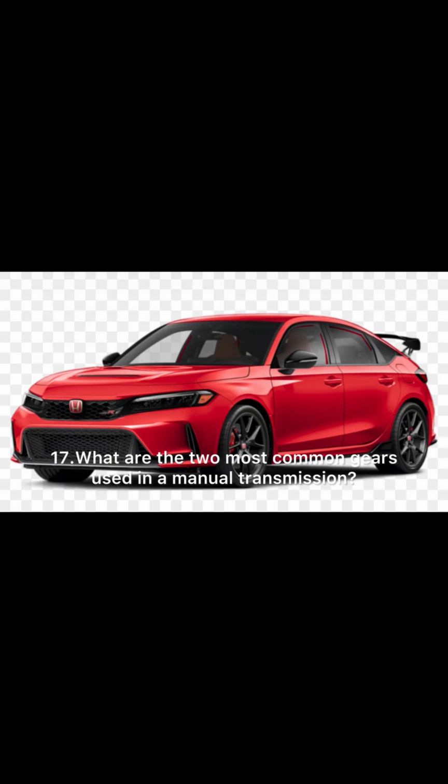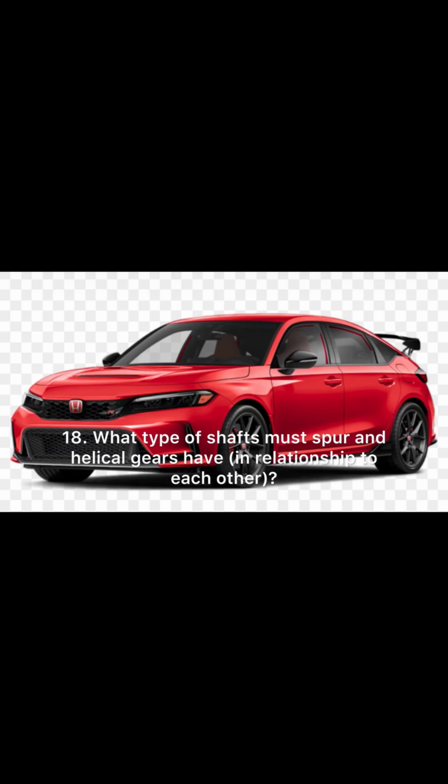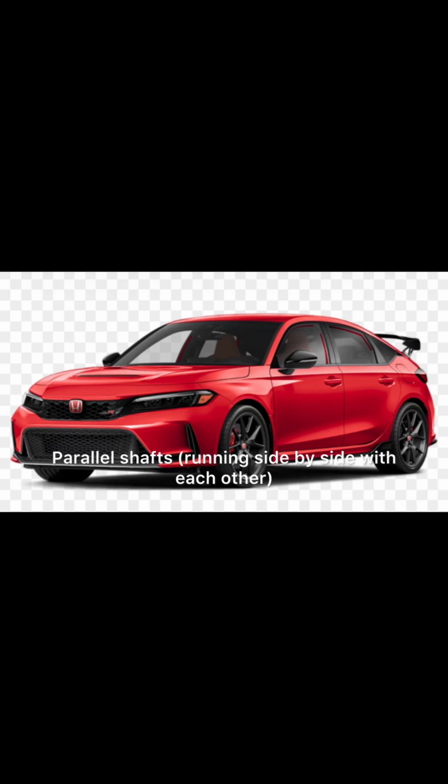17. What are the two most common gears used in a manual transmission? One, spur gear; two, helical gear. 18. What type of shafts must spur and helical gears have in relationship to each other? Parallel shafts running side by side with each other.